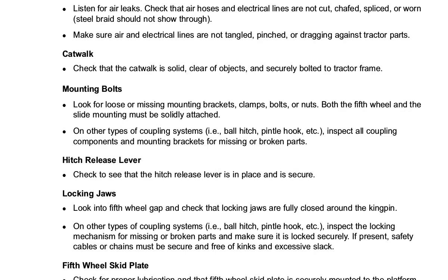Catwalk. Check that the catwalk is solid, clear of objects, and securely bolted to tractor frame. Mounting bolts. Look for loose or missing mounting brackets, clamps, bolts, or nuts.